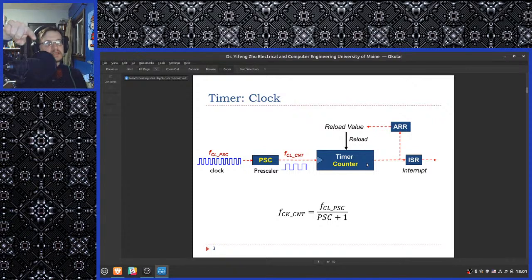Essentially, the timer counter peripheral itself contains a register, which is being incremented every time it receives a clock signal. If you broke this apart and looked at its electronics, it would probably be surprisingly simple. You could probably whip up a circuit diagram for one of these things. Timer chip circuit diagram, maybe we can find one.